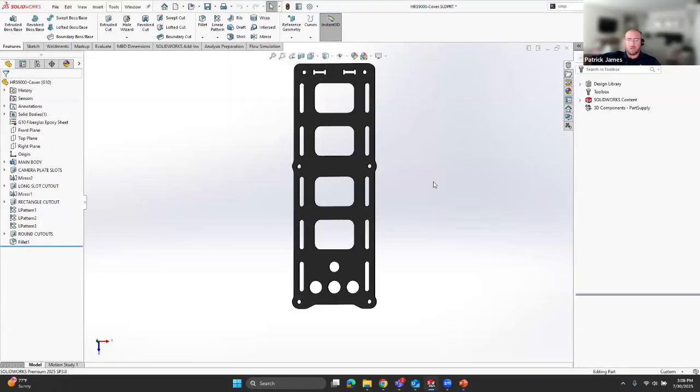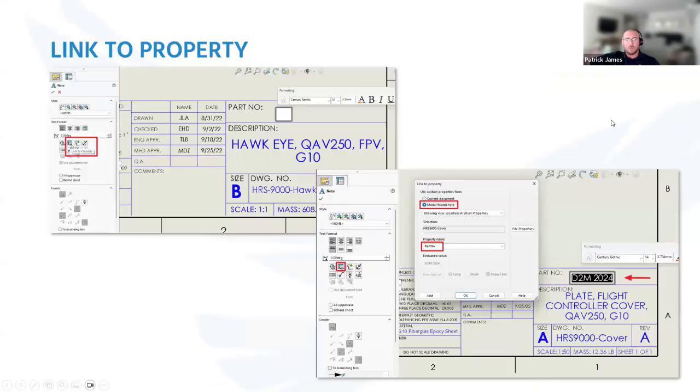So anyway, that is our image quality. Definitely my favorite option for graphics. And if you have anything running slowly, that's the first thing I always check. Really simple solution. If someone cranked it up to get a better screenshot, forgot to turn it down, just crank it back down and everything will load a little faster. If you have a really good graphics card, then maybe it doesn't matter as much for you, but for all of our normal machines, living somewhere in the left third would be my strong recommendation for that one.